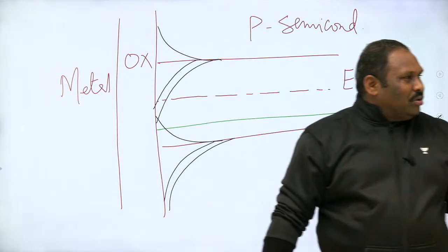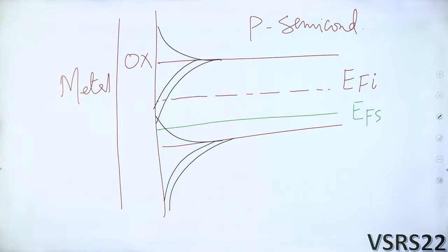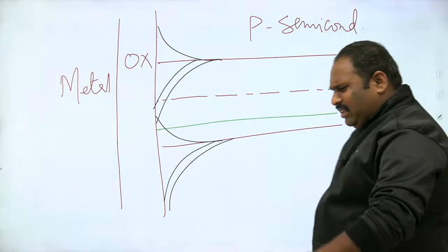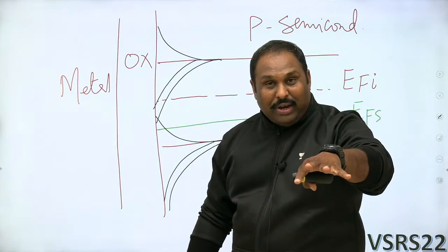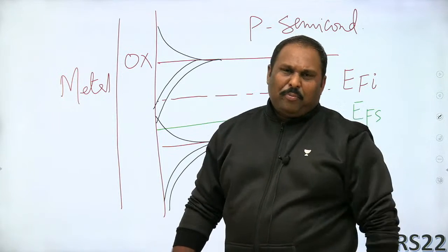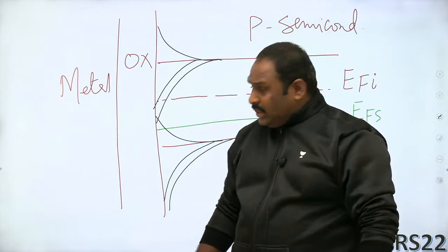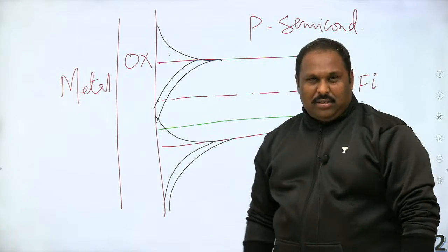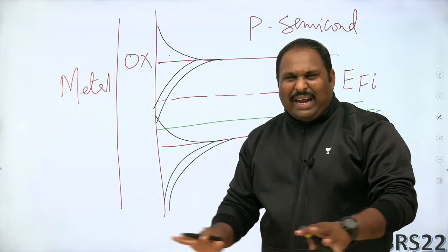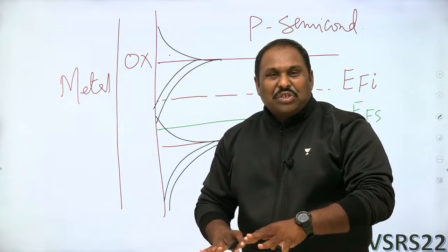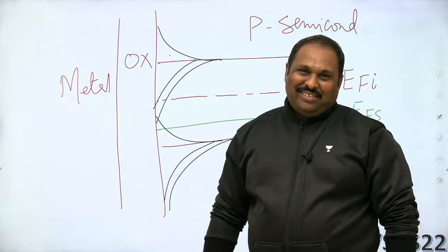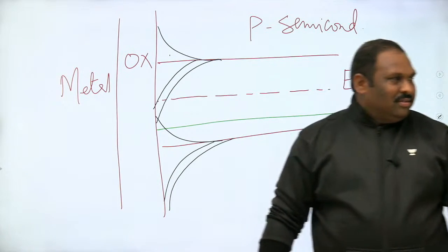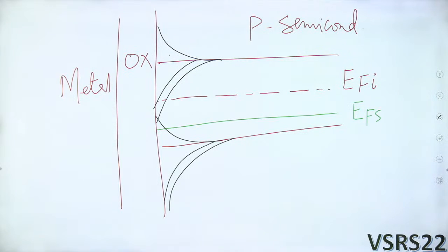I think that's your doubt, AD Rai. If there is so much doping and so much carrier availability, if it is possible in inversion, or if it is possible in accumulation, then they may touch your conduction bands or valence bands, but not practically. The substrate is not that heavily doped that you can supply so many carriers. Any questions, anybody, students? Any doubts, anybody?